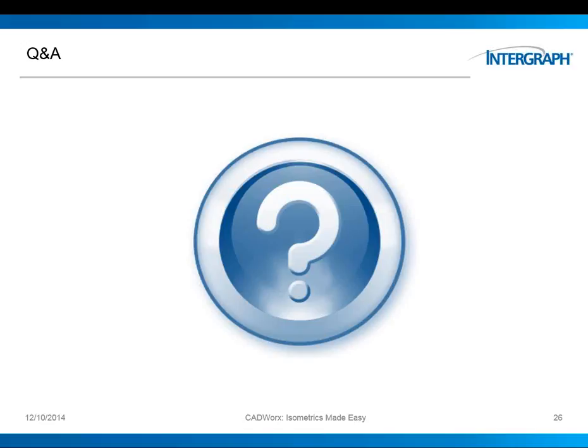Thank you. We already own Isogen for another modeling system we use on some projects. Can we use this license with CADWorx? Another modeling system. Okay. The answer basically is no. Isogen is licensed for use on specific modeling systems, and these licenses cannot be interchanged. For example, you cannot use the Isogen in Caesar2 to create ISOs in another application. And besides, Isogen is already included in CADWorx anyway.